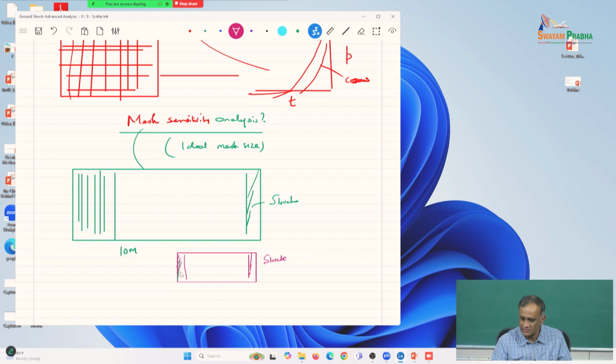So, this surface, your TNT is still here. Up to here it will use Friedlander equations. So, probably up to 8 or 9 meters you are making some assumptions there, you can check. 8 or 9 meters you can use, and then from here to here you can use air mesh.